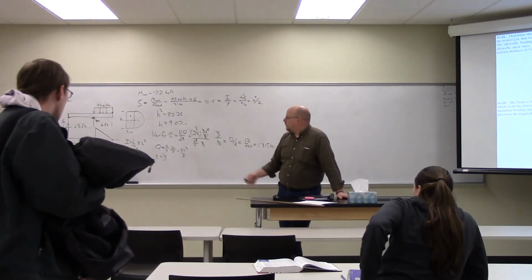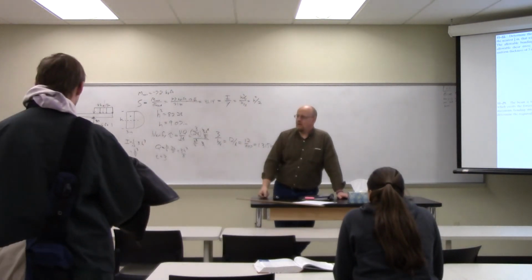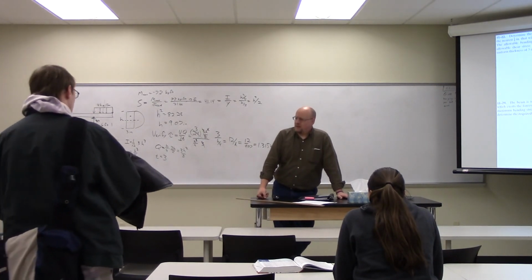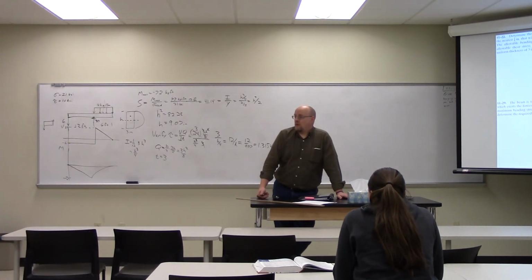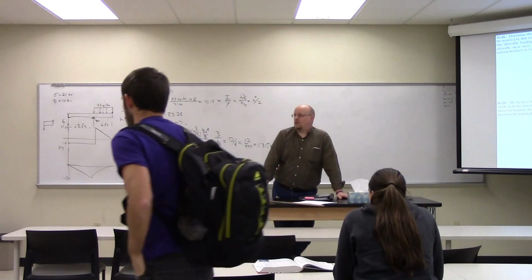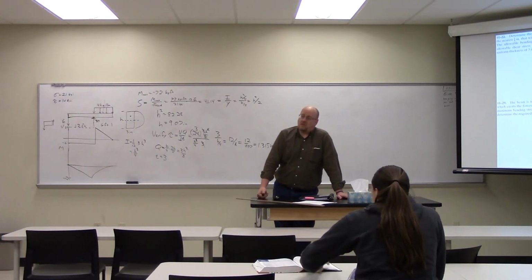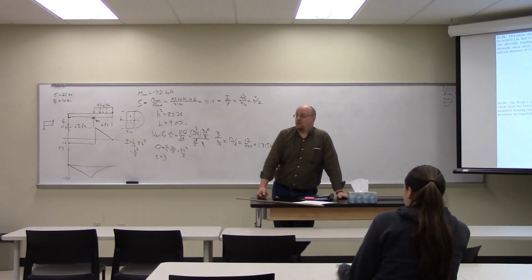If you had a beam that was 4 feet wide and 12 inches high, it'd be enormously strong. It'd be incredibly heavy, right, and incredibly expensive to manufacture as well. So you'd much rather have the I-beam, which is a fraction of the mass and cost, and yet still has a pretty significant proportion of the total bending strength.